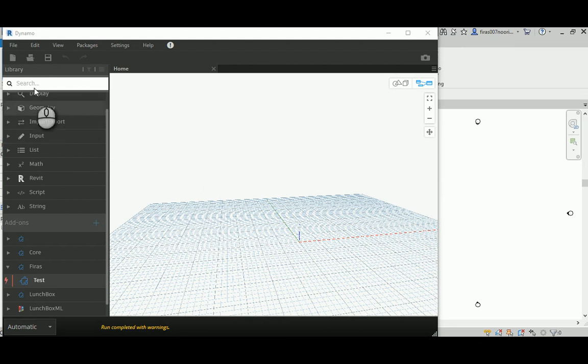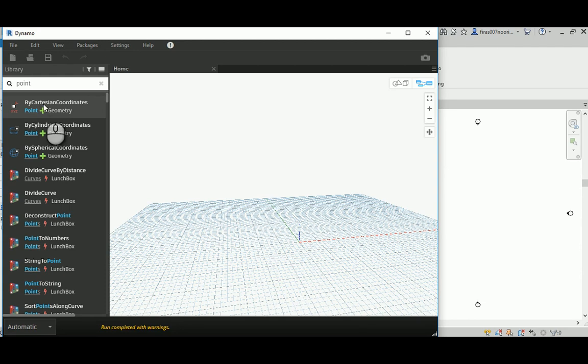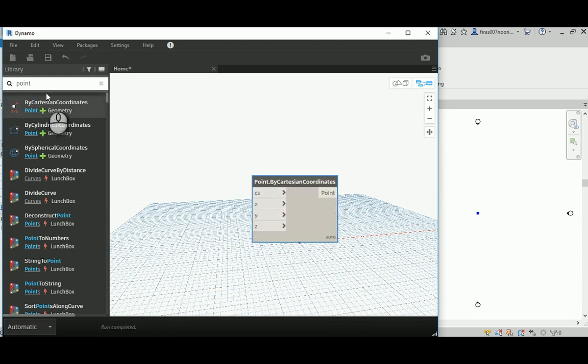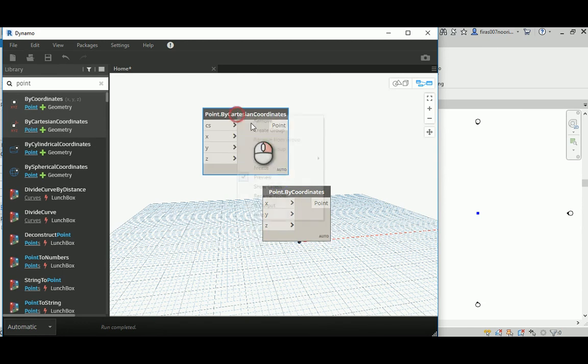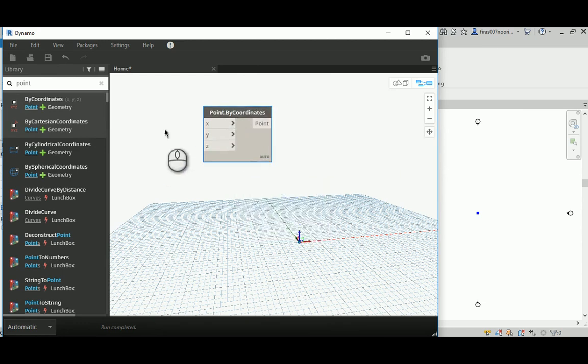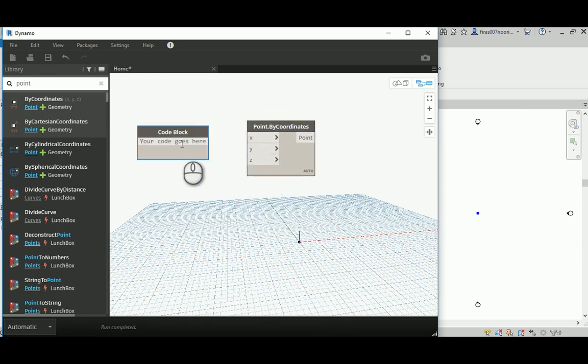So first you go ahead and create your own points, which for the current condition will be within the Dynamo environment, not in a custom node system. As I said, I'm just going to delete this one. I'm going to keep that one, and just for simplicity I'm going to go from 0 to 20 and jump each 10, so one jump, two jumps.